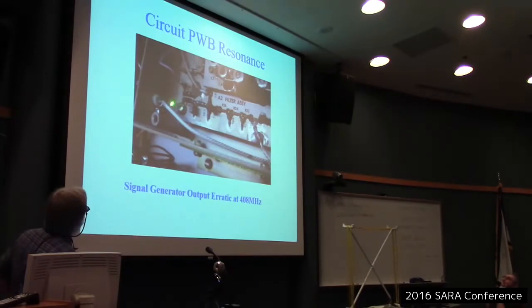Now this was another one that was particularly interesting. It was a surplus signal generator from AIL Instruments or something. But anyway, it had intermittent performance. You could tap on the top of the case and it quit. Well, this coax cable that was here, this is a new one. But the old one that was there had a little plastic thing that was holding the shield in place, a pressure connection. And the plastic had cracked, and I couldn't get a replacement part for that. It was 30 years old. So I just soldered a new coax cable in here and said, that ought to have it fixed up. Made the new one a little bit longer so there was enough room to put it in the box. And it turned out that caused an odd thing.